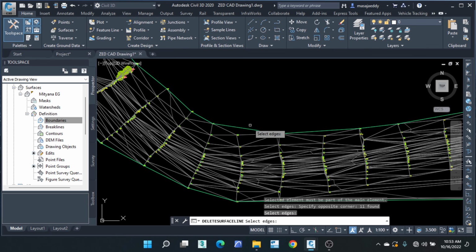So the other frequently asked question that I've received is: what is the difference between the boundary and the border? What you see in the green is the border, right? And then you drew a polyline and created a boundary using a polyline, right? We created that and defined it as a boundary, and that boundary was restricting our border from getting outside of that area, right? So it created a new border along that boundary. It's a restriction.